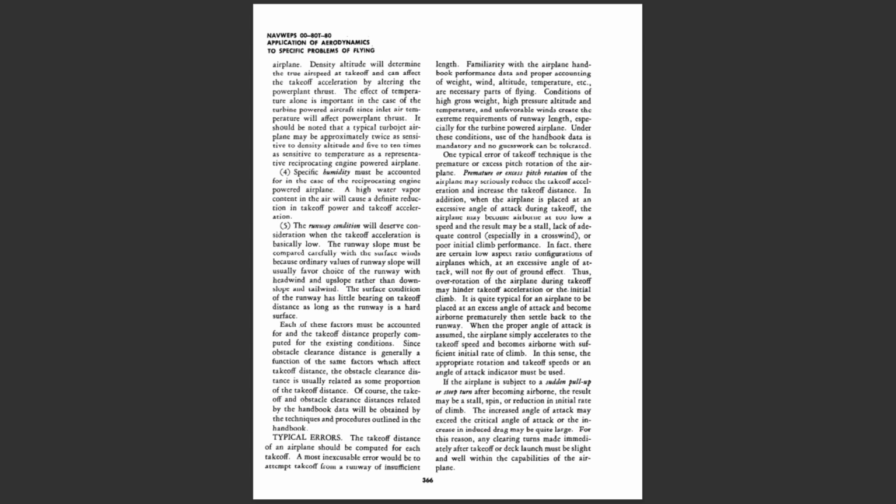When the proper angle of attack is assumed, the airplane simply accelerates to the takeoff speed and becomes airborne with sufficient initial rate of climb. In this sense, the appropriate rotation and takeoff speeds or an angle of attack indicator must be used. If the airplane is subject to a sudden pull-up or steep turn after becoming airborne, the result may be a stall, spin, or reduction in initial rate of climb.